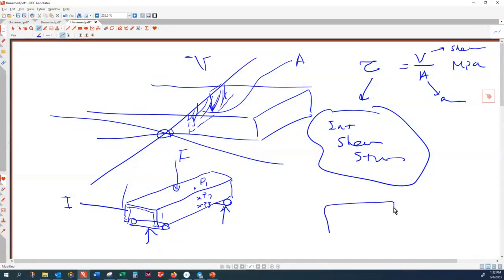For that composite section, how do you calculate the moment of inertia? First, you have to decompose it into two shapes: one big rectangle, one small triangle. That one minus this one. But then you have to find the neutral plane axis.